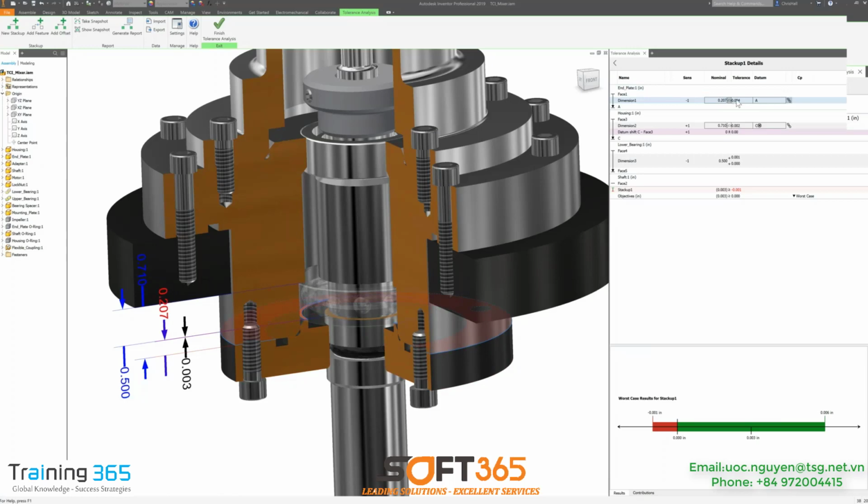Applied. That information was used and linked in the stack up. Also the housing itself as well. And you can see right now that I'm between 1,000th and 6,000ths of an inch. But if I change to root sum squared for a minute here, you can see from that particular result, I'm in pretty good shape.